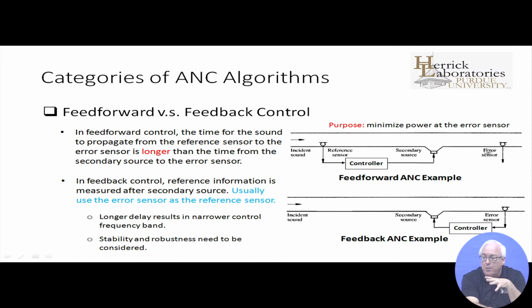In the automotive context, for example, we were talking yesterday about structure-borne noise being important at relatively low frequencies, say below 500 hertz. So a major mechanism involves vibration of the vehicle hub, or the wheel hub, that then connects through the suspension into the interior of the vehicle.